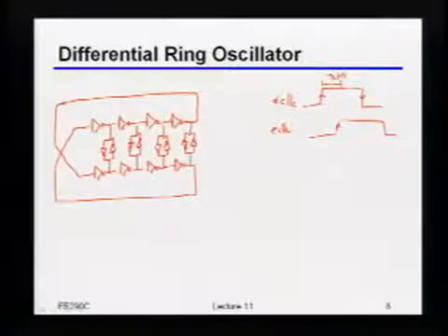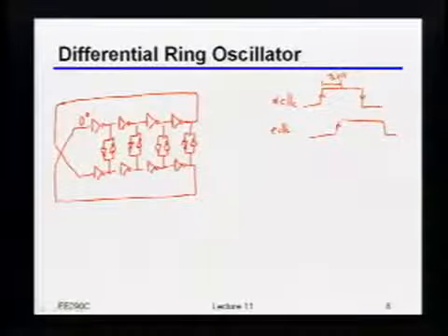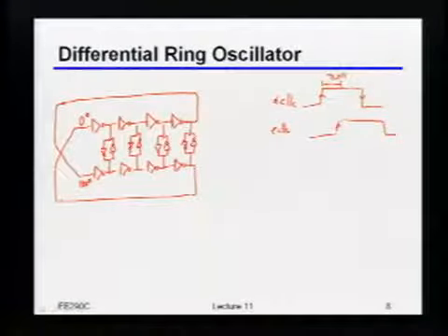Again, just to make sure everybody is clear as to how this thing works, if I called that one right there 0 degrees, actually, sorry, let me shift it back by 1. If I called this here 0 degrees, then that would say that this is 180 degrees. And now each inverter delay gives you 180 plus a 45-degree phase shift.